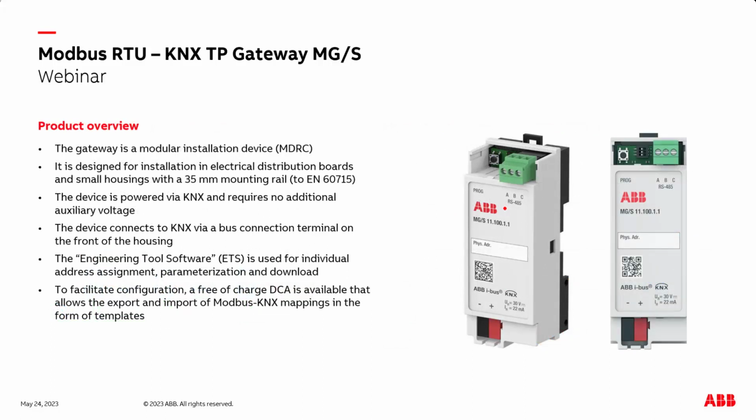Then let's come to the product overview. You see the pictures on the right side. It is a standard modular DIN rail installation device which can be mounted in a standard cabinet or distribution board with a 35mm mounting rail. The device is only powered via KNX and requires no additional auxiliary voltage.